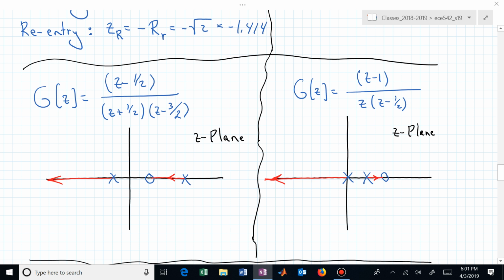That's a pretty easy root locus, as is the next one to the right. But do you see that I've put arrowheads or arrows? We start our root locus branches at the open loop poles, and we finish on the finite zeros, and we finish at zeros at infinity.